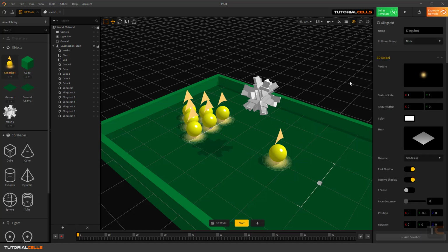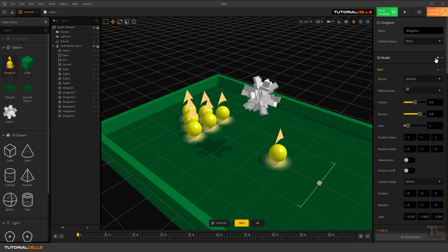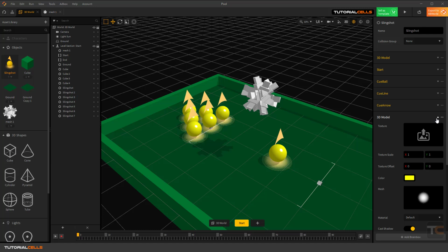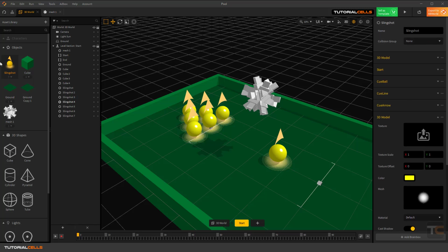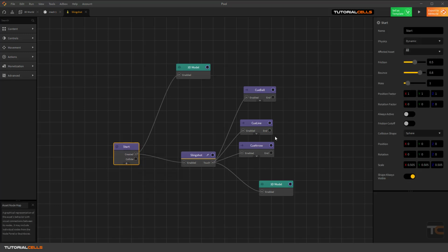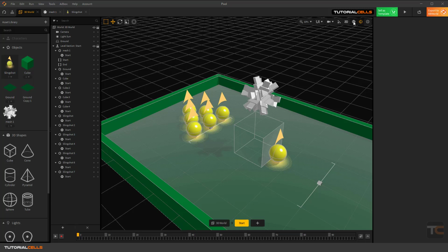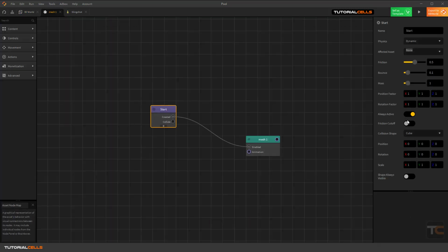If you select this, you can tell the software, for better understanding, you can close all of them, because it has lots of things attached to that 3D model. I think you have to double click and select the start of that and tell always visible. And then you can see the collision shape of them is always visible.